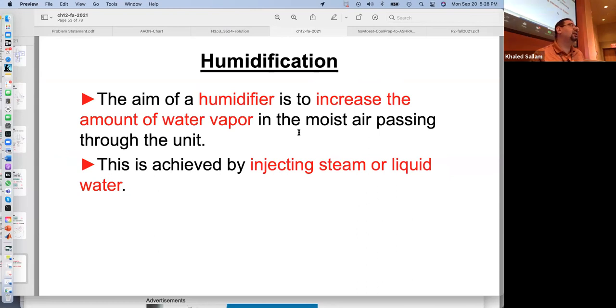And just to be on the safe side, let's not even inject hot water, because you may think, well, hot water, but I still need my hfg, right? Even if hf is high because I'm spraying water at 80 degrees, it's still water. And to get the hfg, which is a big deal, the air will have to pay, the air temperature will drop. But what if we actually inject steam? Then it's a done deal. You inject steam, of course, the temperature will increase, right? Because it's ready to go.